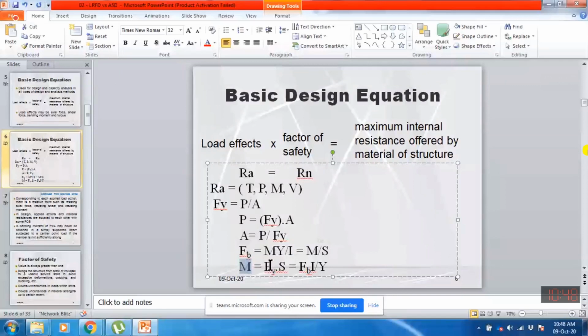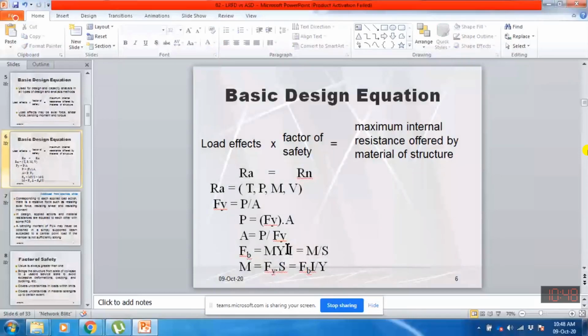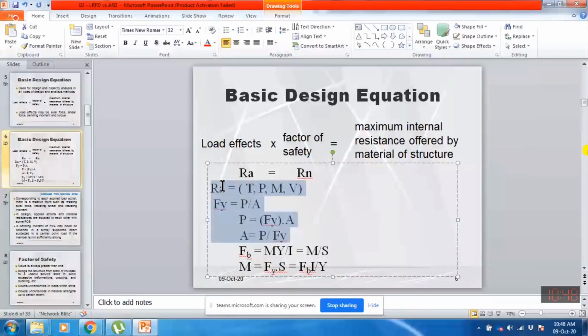Actually, this equation is a perfectly balanced equation. It means that, I told you that as a structural engineer, we may have a lot of approximation and assumption in computing the material strength, because this Fy, when we buy certain material, we determine its yield strength in the laboratory. It means that its yield strength sometimes may not be properly computed, and sometimes we also have assumption in the applied loading. So it means that this equation is actually at collapse state.